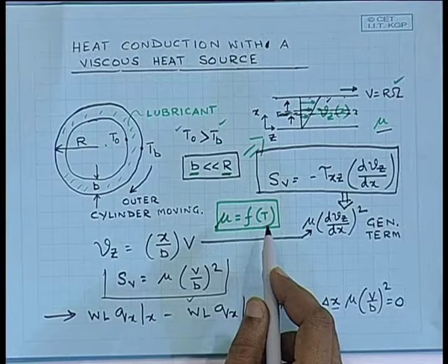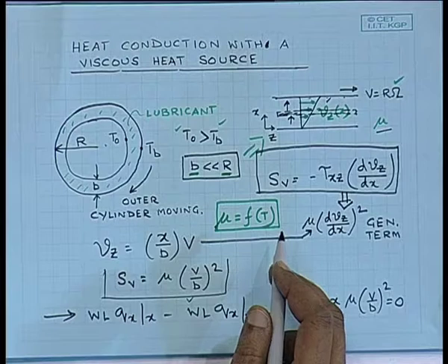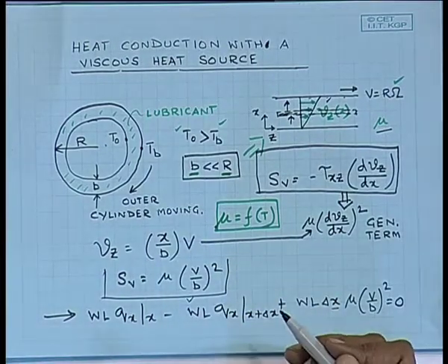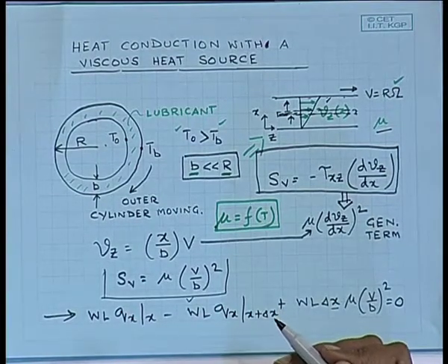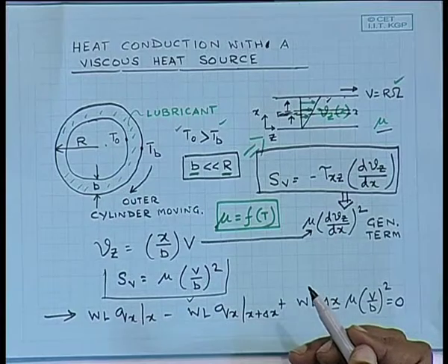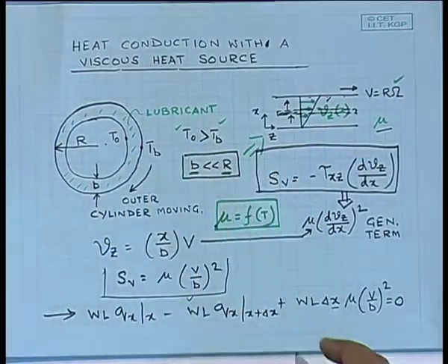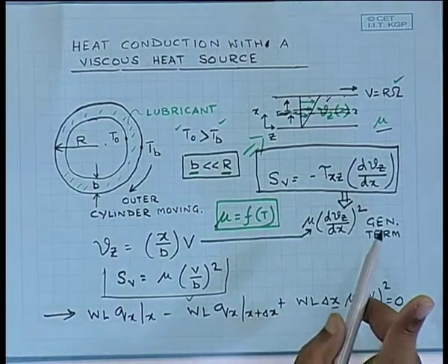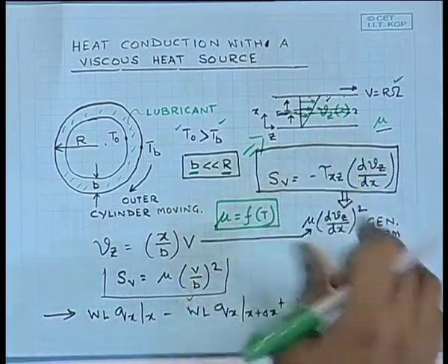So, my hydrodynamic solution is dependent on the thermal problem, and when I come to the thermal problem, without knowing the velocity gradient at a specific point, I wouldn't be able to solve for the temperature profile. So, that makes even this very simple problem coupled, and just one assumption that mu is independent would make these two processes decoupled.